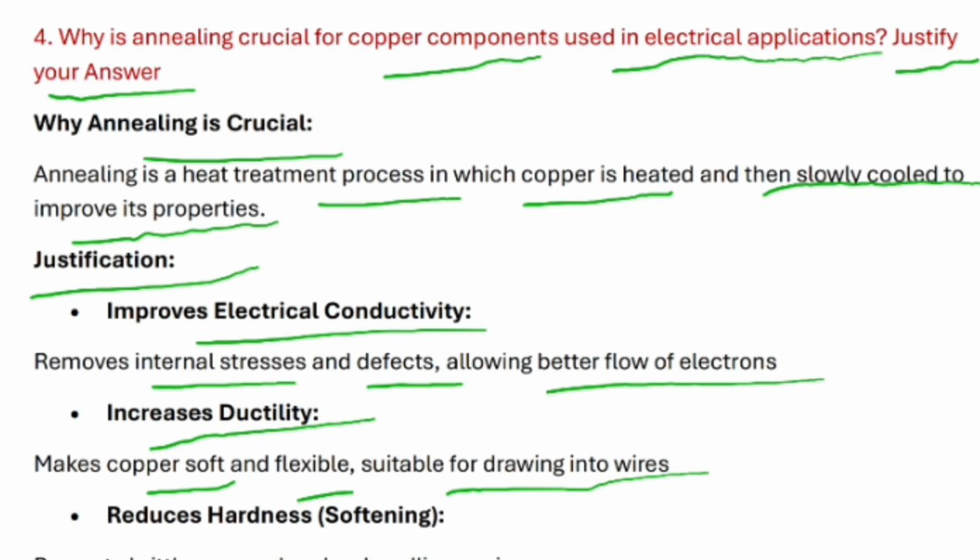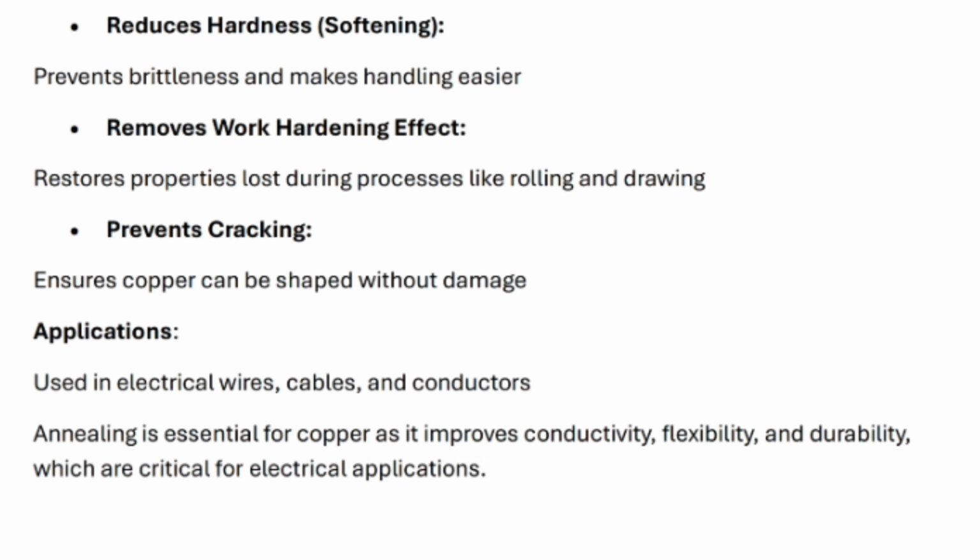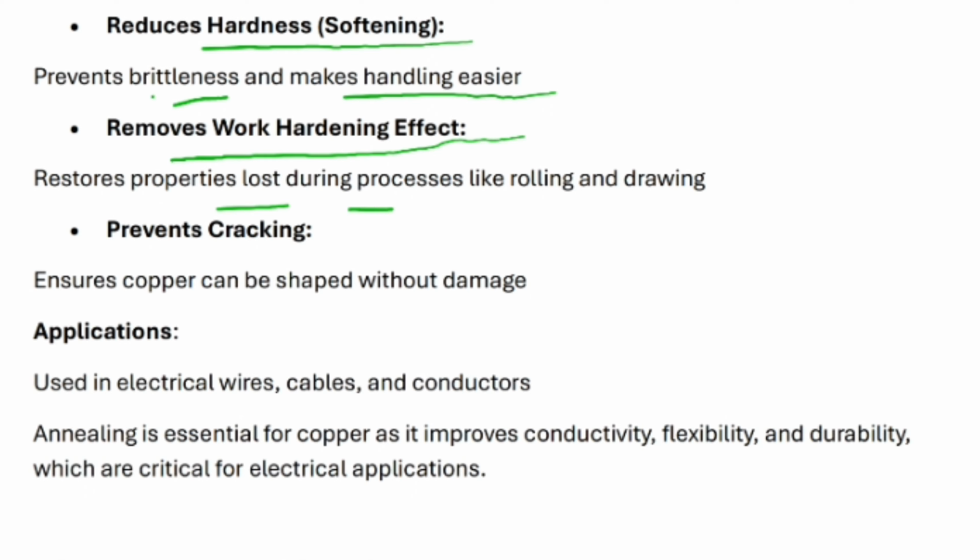It is suitable for drawing into wires. Next is to reduce the hardness, I think it's softening to prevent brittleness and make handling easier. Remove work hardening effect. Restore the properties lost during a process like rolling and drawing. And next we say prevent cracks. Ensure it can be shaped without damage.